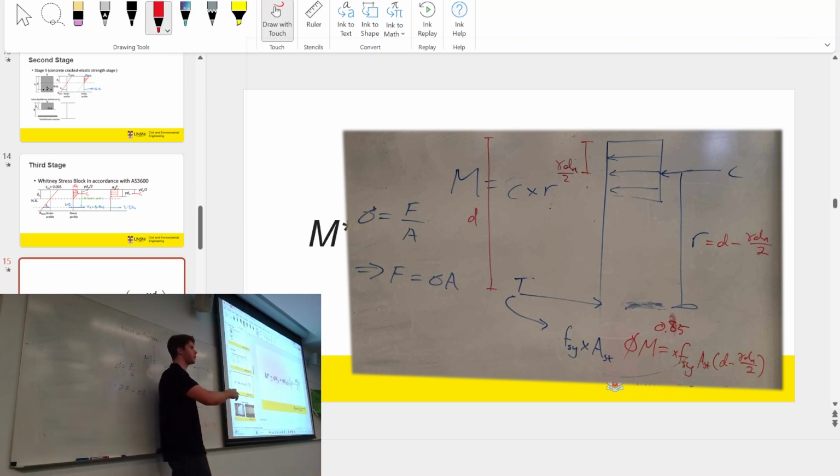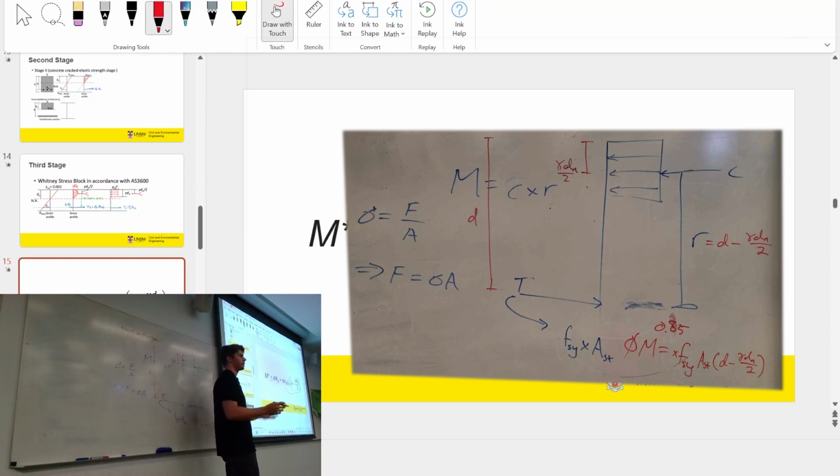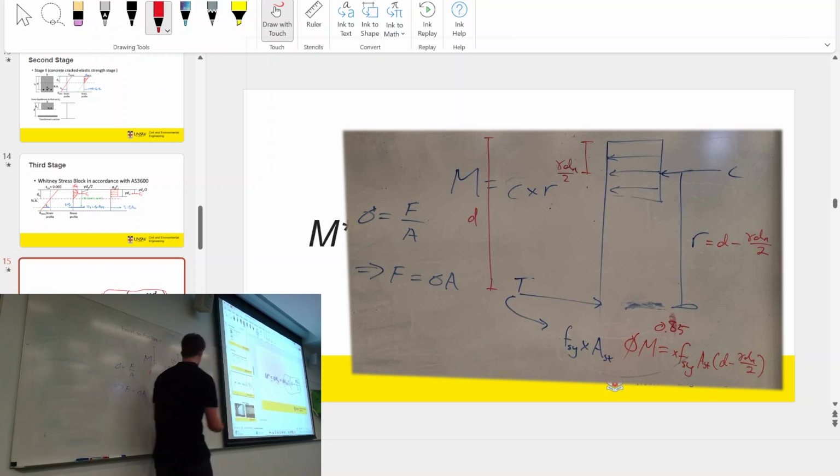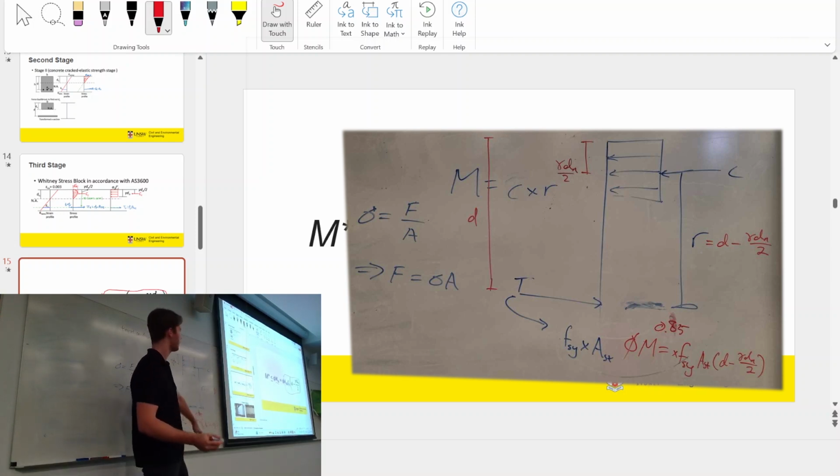Now, remember from before when we talked about limit state design, we want to make the section seem worse than it really is. So all we really do is apply like 0.9 to this, or actually from the code, I think it should be 0.85. Yeah. So we multiply 0.85 times this. And that's just your phi factor. That's what that phi symbol there looks like.